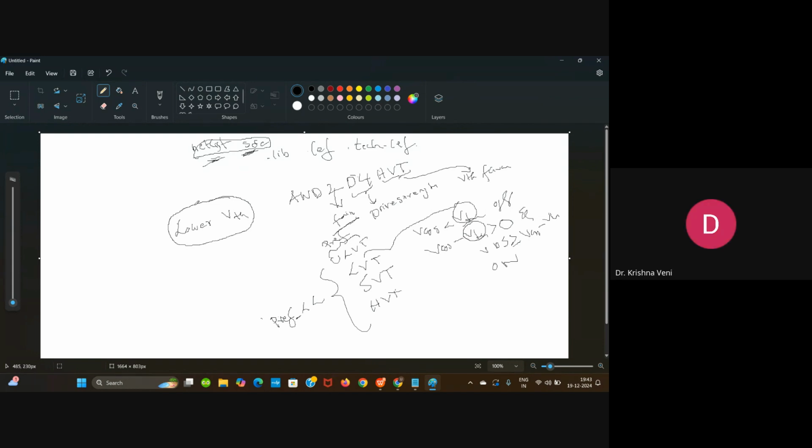It's very tricky. Power consumption. Exactly, leakage, sir. So if you use a lower VTH, then there will be leakage. So how will the leakage occur? The electrons should flow from source to drain, but what happens when there is a leakage? It will try to penetrate through the substrate because it is also connected to the ground terminal. That will be the leakage here.